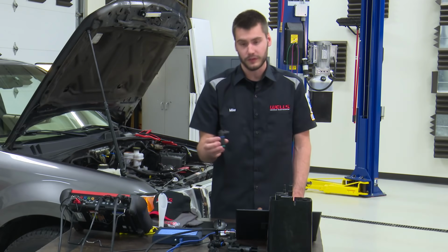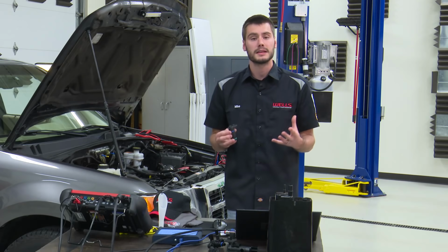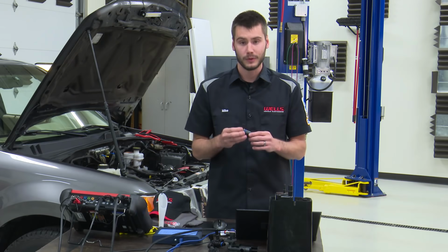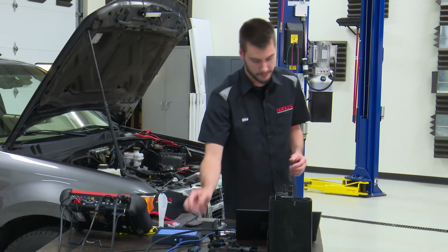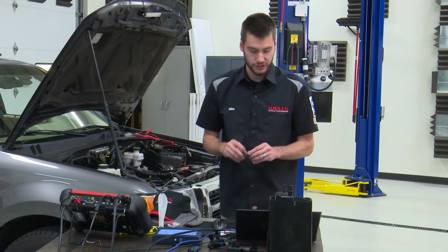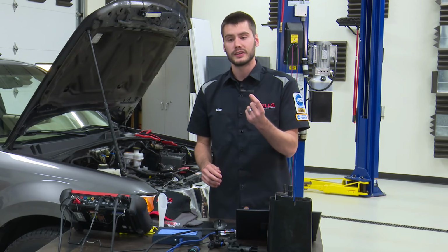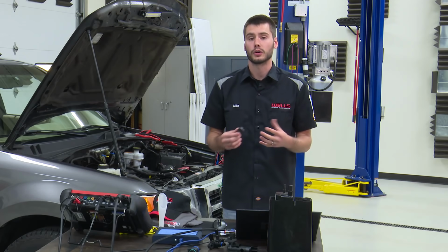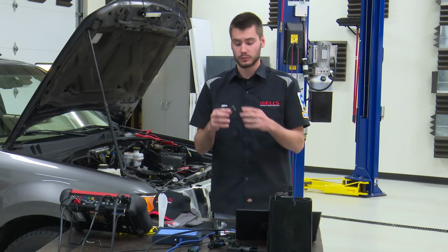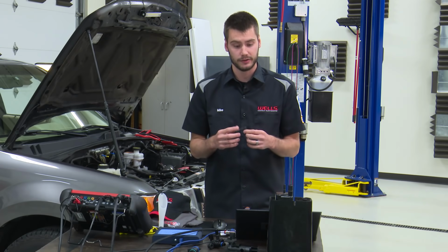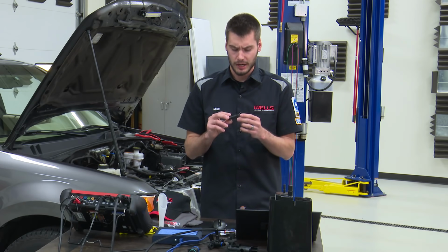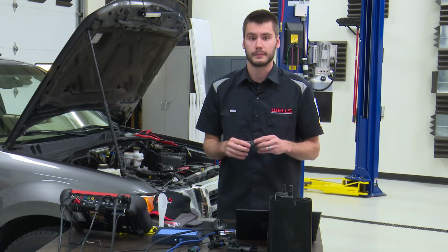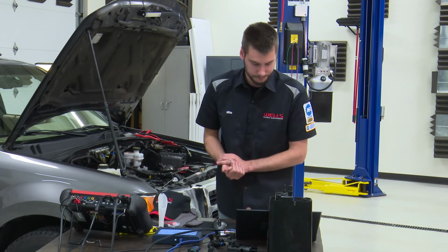But it's important to note that because we have a vented system, it doesn't mean we're venting fuel vapors. We don't have a vented gas cap or anything like that. We're venting only fresh air, okay? From there, we have a fuel tank pressure sensor. This is the brains behind the operation. This is monitoring the pressure inside of the tank, inside of the lines, inside of the system for leaks, I guess. This is what we're using to check for leaks and check for system integrity. The computer watches the pressure on this, which operates very similar to a MAP sensor, a 3-wire sensor, and it's going to watch this over time to check for leaks. I'm going to get into leaks in a little bit here.